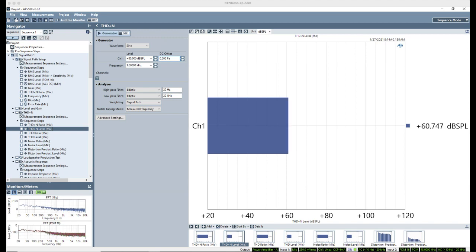And then finally, a comment. I just measured a quarter-inch measurement microphone yesterday. Pressure mic at 90 shows -1 dB at 20 kilohertz, but about +6 dB at 80 kilohertz. And yes, that is entirely true. It depends on the pressure mic. Generally speaking, acoustically for sound applications, we're not too concerned about 80 kilohertz. It's also quite likely that the pressure mic is not flat. They do roll off at a certain rate, they don't tend to be flat all the way to their full bandwidth.